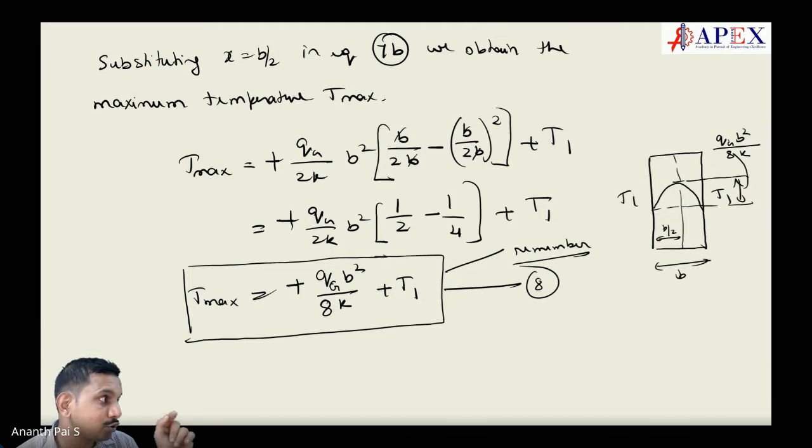Here you should not take electrical work done as Q, you should take it as W. If you take it as W in the first law, only then will things go properly. Otherwise, they will not. That's how it works. Make sense? So it's important that you understand it better.